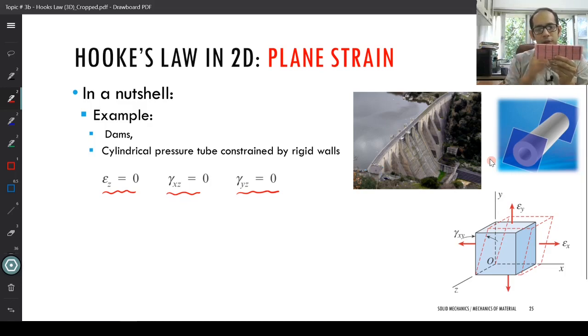So when you are heating this bar, and if you have it clamped over here, then in that particular case you can have expansion about the y axis, you can have expansion about the x axis over here, but about the z axis, since it is clamped, you're not allowing any movement, right? So all the strains, the epsilon z which you are having along these two z axes over here, are restricted. Your gamma xz is restricted, and gamma yz is also restricted, right?